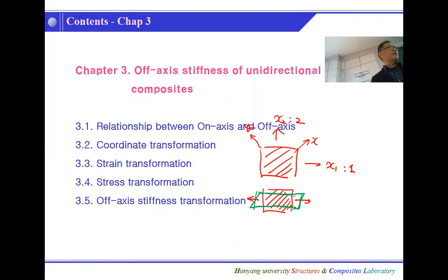Shear strain means that this will have a change in angle. So here we apply this stress, which will be called sigma 1 rather than sigma x. Okay, with sigma 1 we now have epsilon 1 extension and contraction and shear strain, all 3 terms.